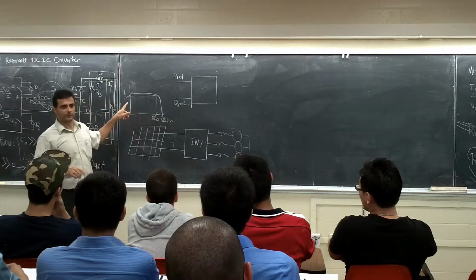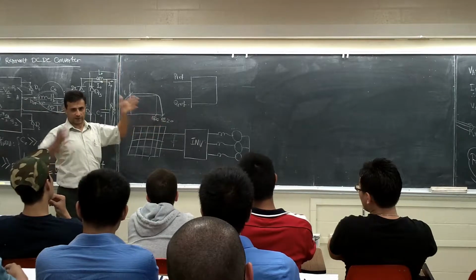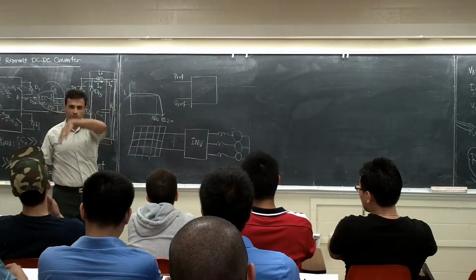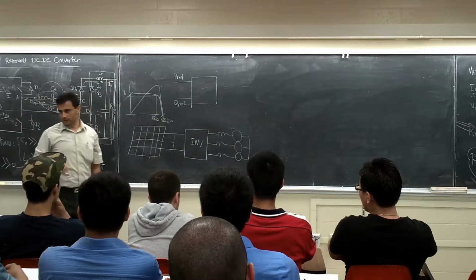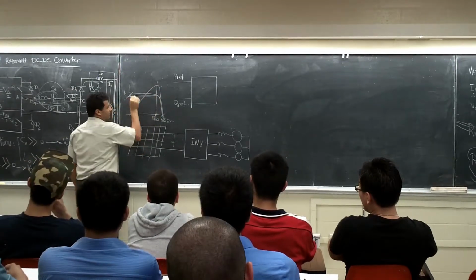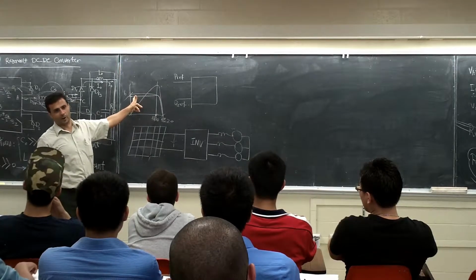Create another column. What to do? This one times this one. In the Excel sheet, you have one column for voltage, one column for the current. Multiply them by each other, it's going to be power. It's going to give you this one. Just find out how much this one is, because for the PC model, you need this one. It's going to ask you how much the VMPPT and IMPPT are.